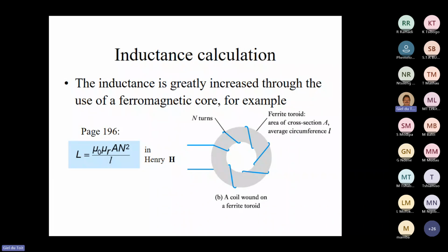So the quicker you switch off this current in the coil, the higher the back EMF, the back voltage, will be. I can use a 1.5 volt battery, switch it very fast, and then I can generate 200,000 volts with that. That is amazing. So this is a tool you can create a lot of different things with.